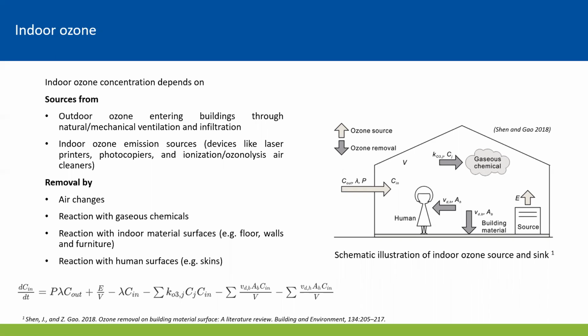The ozone concentration in indoor environments can be estimated by this single zone mass balance model. In this presentation, I will just focus on the indoor ozone source from indoor ozone emission devices and the surface removal by building materials.